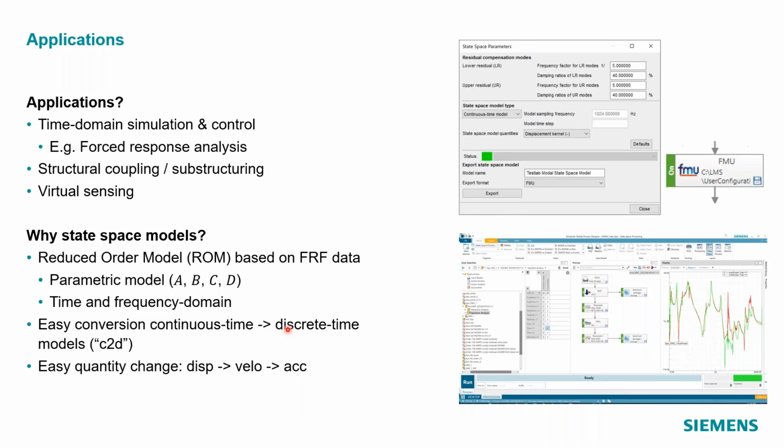In the software, I will do first the generation of a state space model. I will export it to an FMU, and then I will load the FMU in TestLab and do some simulations, some time domain simulations to illustrate what we can do with these models.